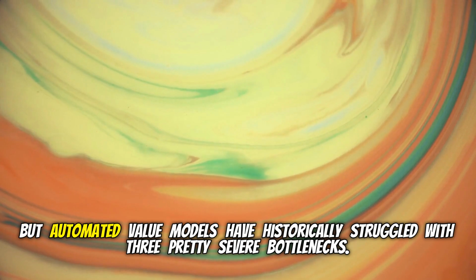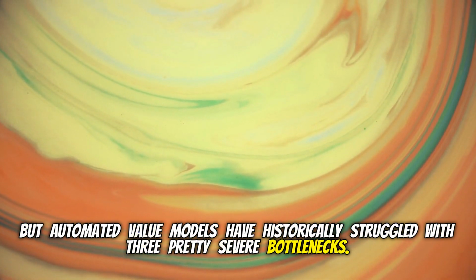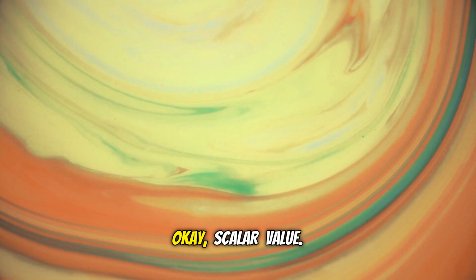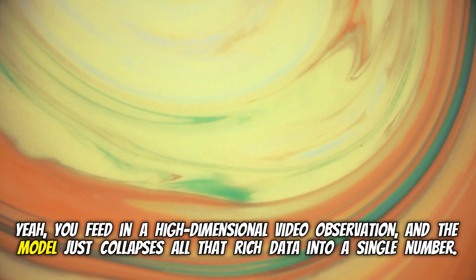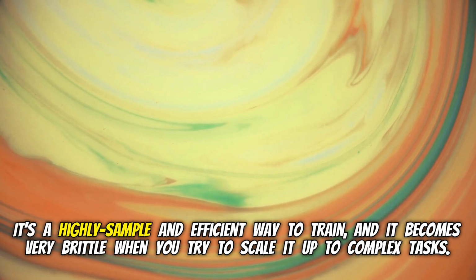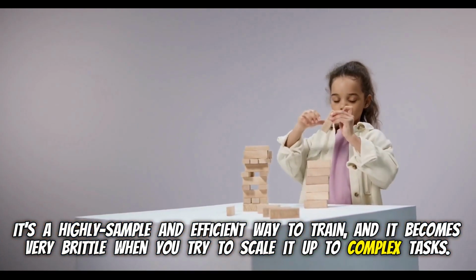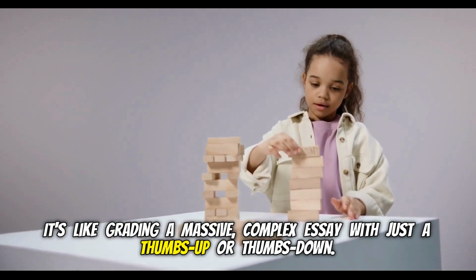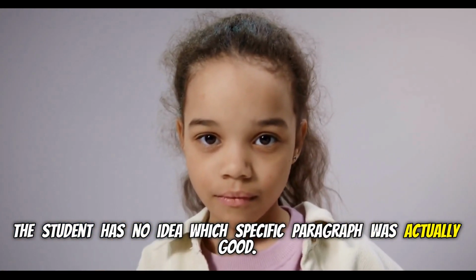Right. But automated value models have historically struggled with 3 pretty severe bottlenecks. The first is a reliance on simple scalar value supervision. Okay, scalar value. Yeah, you feed in a high-dimensional video observation, and the model just collapses all that rich data into a single number. Wow. It's a highly sample-inefficient way to train, and it becomes very brittle when you try to scale it up to complex tasks. It's like grading a massive, complex essay with just a thumbs up or thumbs down. Exactly. The student has no idea which specific paragraph was actually good.